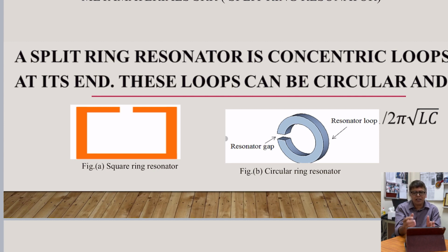We can call these absorbers receive only antennas. Now in case of energy harvesting, the received energy or received power PR will be converted using a rectifier circuit into DC voltage, and then the DC voltage will be connected to the load, which can be a small IoT device. The main problem here is that the received signal of a receive only antenna is very small, so very little power will be converted into the corresponding DC voltage.